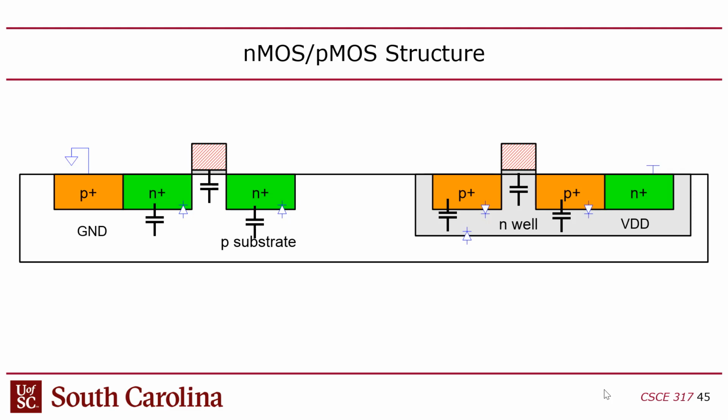But one thing I haven't talked about yet is there are also capacitors in the diffusion areas. Because as it turns out, a diode that is reverse biased, meaning that the voltage of the cathode versus the anode is positive, won't send current through it, but it will create a capacitor. When the charge carriers are repulsed away from the junction in the diode, that area between the charge carriers and the junction becomes the middle part of a capacitor, the insulator part of a capacitor. So you get capacitance here.